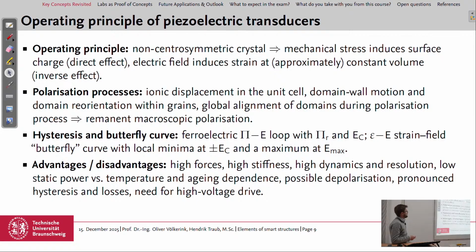Then we moved over to the operating principle of piezoelectric transducers. The operating principle is that we have a non-centrosymmetric crystal, so mechanical stresses induce surface charge, which is the direct piezoelectric effect, and the other way around, an electric field induces a strain at approximately constant volume. This is the inverse effect we use for actuation.